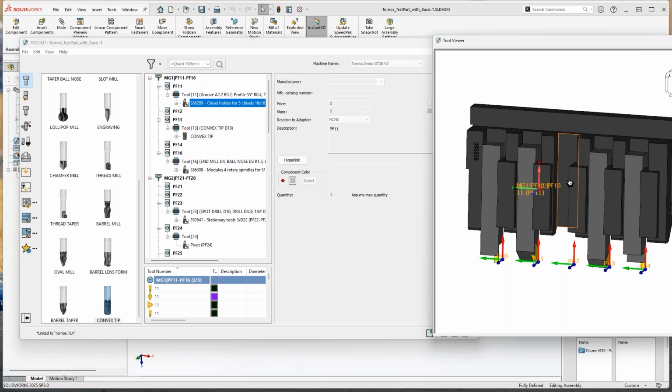Many users ask: in milling we have the outside holder length, and in a milling tool this is quite easy to define. But what about turning tools? For turning tools, you can have a very complex holder, and it's not really clear what the stick out point is. Sometimes it goes from the joint, sometimes it doesn't. Sometimes it obviously needs to be modified. We never had this option until the 2025 version, and I want to show you how you can use it.